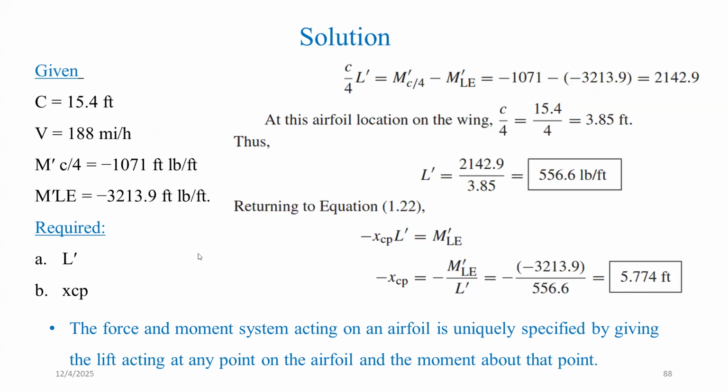So the force and moment system acting on the aerofoil is uniquely specified by giving the lift acting at any point on the aerofoil and the moment about that point.